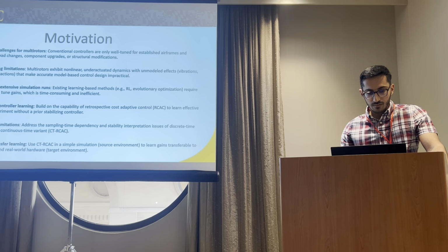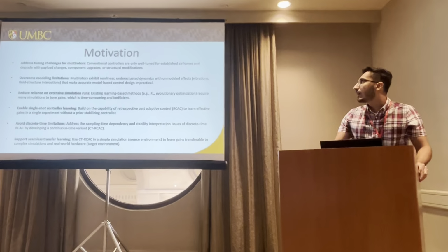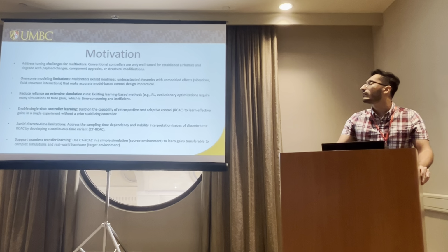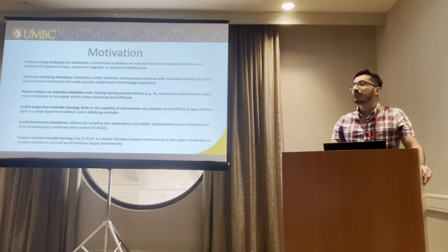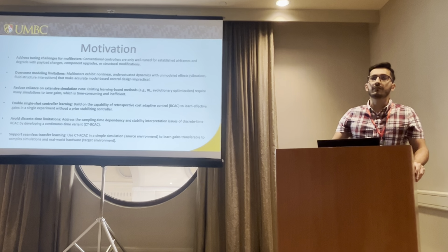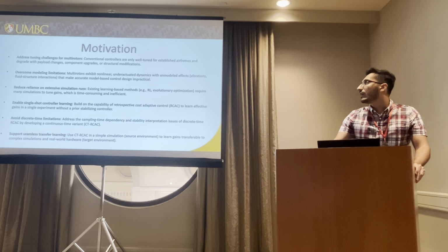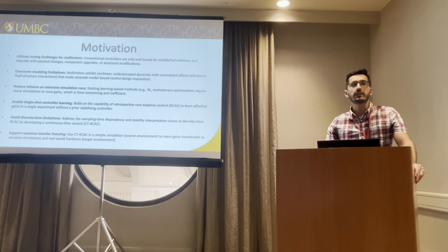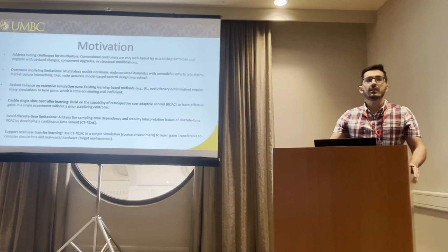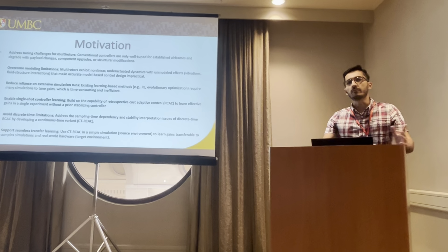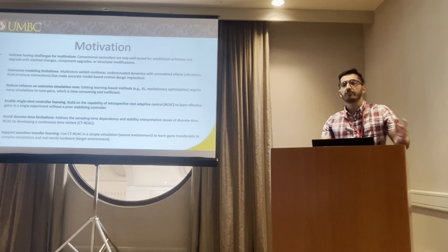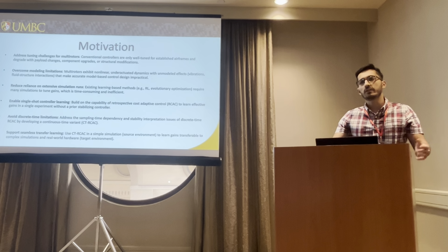The motivation behind this work is that the most commonly used flight controllers like Pixhawk are well tuned for well-established airframes, for example the Holybro X500 and DJI F450. They are well tuned for these commonly used airframes, but if you make any change in the structure, the propellers, or the motors of your multirotor, the performance of the controller would degrade in comparison to the nominal controller. So there's a need for retuning.